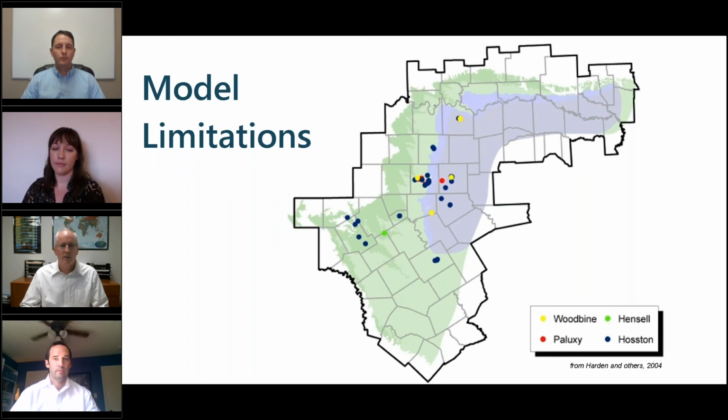we just have to face the facts that we often have very sparse data availability. You can't generally see an aquifer. You can look at it in individual well bores. You can measure certain properties. There are other parameters that you really can't measure. Recharge, evapotranspiration, groundwater surface water interaction are difficult to directly measure. So as part of the process of putting together vast arrays of data for your model, you have to make a lot of assumptions, and assumptions are inherent in the process.